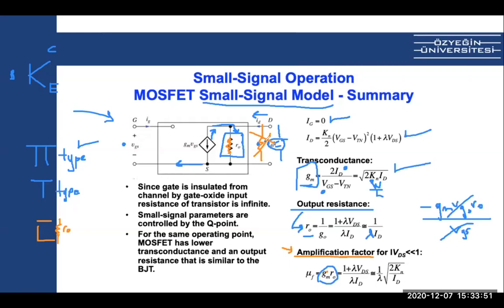But when we connect the load here in parallel, whether R0 is big or not doesn't really matter that much. I mean, it matters, but if we connect a small resistance here, let's say 5 ohm, this R0 won't really have any effect, because 5 ohm in parallel with a big R0, let's say 100 ohms or 1000 ohms, becomes about 4.99, right?